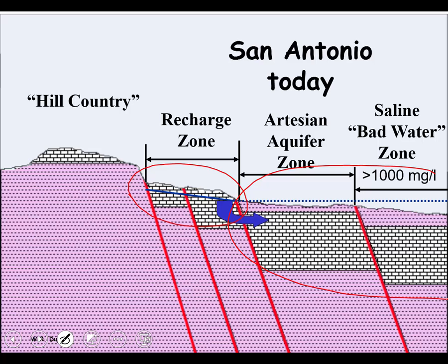Notice also that this potentiometric surface is controlled by the level of the water table in the recharge zone. Okay? So anything that you do in the recharge zone to lower the water table will also lower the potentiometric surface. And one of the things you really hate if you're using a confined aquifer, if you have a flowing artesian well, is for that pressure surface to drop below the ground. Because that means now you have to install pumps to get that water up.